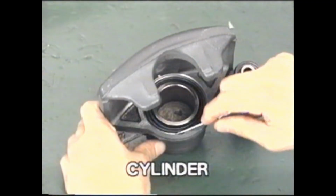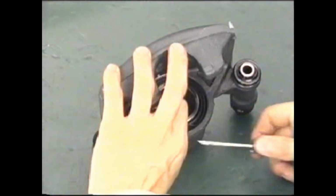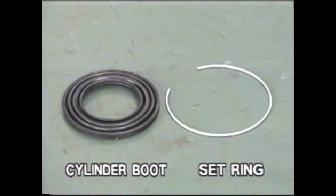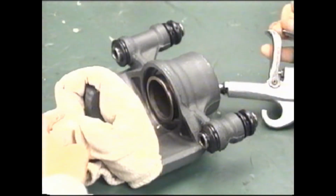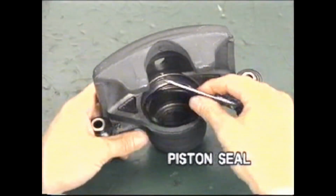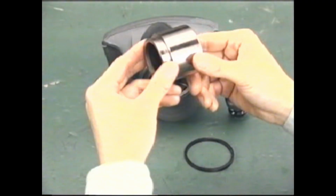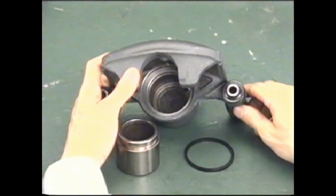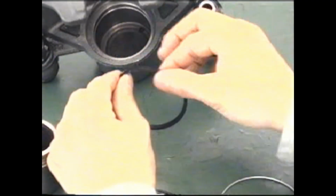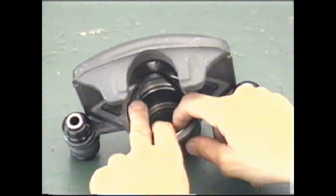Then disassemble the cylinder. Remove the set ring and the cylinder boot using a screwdriver. Put a piece of cloth or equivalent between the piston and the cylinder. Use compressed air to remove the piston from the cylinder. Do not place your fingers in front of the piston when using compressed air. Remove the piston seal using a screwdriver and the disassembling is completed. Observe to make sure there is no damage to the piston or piston cups. When assembling, apply grease to the piston seal, piston, cylinder boot, and install the set ring.